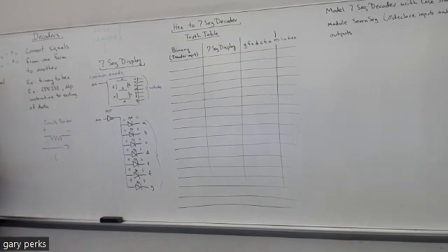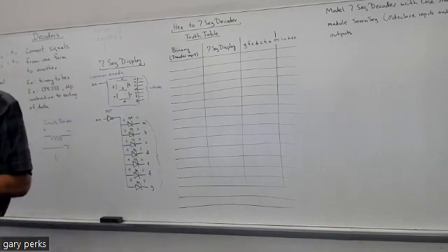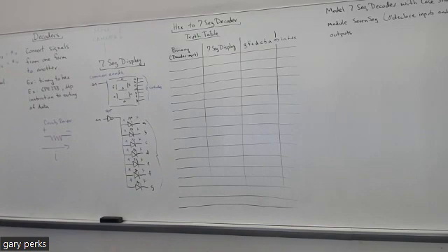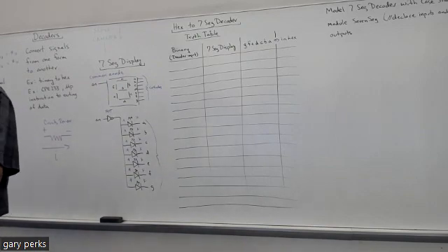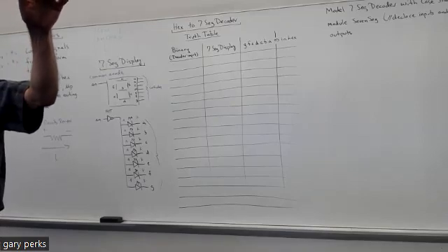Yeah, it would be like this, right? Because as current flows through a resistor, you get a voltage drop. So as current flows, you're going from a higher voltage to a lower voltage. Do resistors ever supply power? No, they only absorb power. Anytime you get a voltage drop, that's absorbing power. In order to supply power, you'd have to have a voltage rise, with current going from the lower voltage to the higher voltage, right?